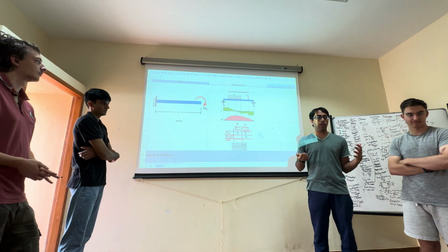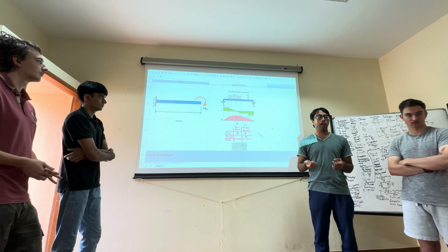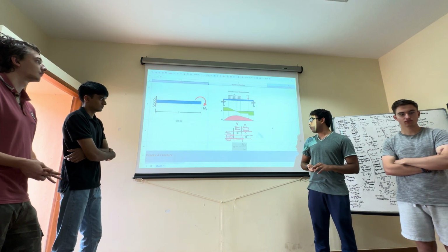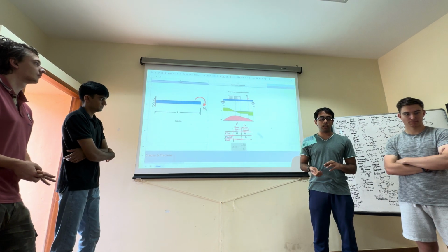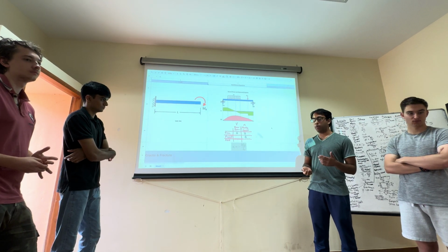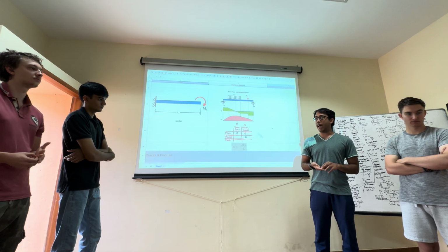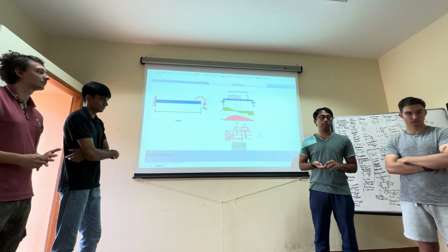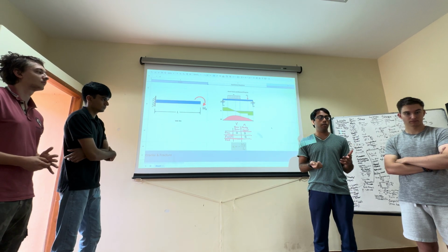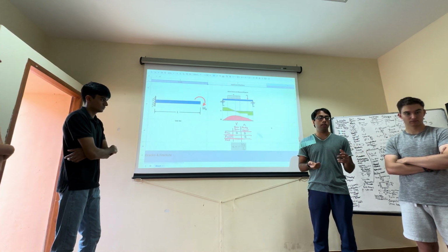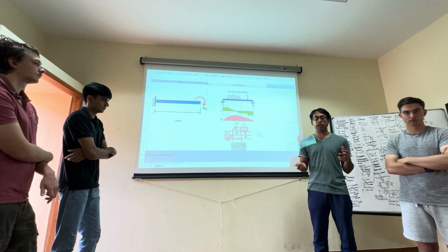And using these equations, we can actually derive both a stress from this, as well as later we'll see a deformation. And so for the stress, we have an example where the moment in the z direction multiplied by y divided by the second moment of area will give us a stress in the xx. So it's going to be a uniaxial stress here. And while we have these equations, in order to fully solve them, to find displacement as an example of deformation, we need to know the boundary conditions on which the structure is existing.